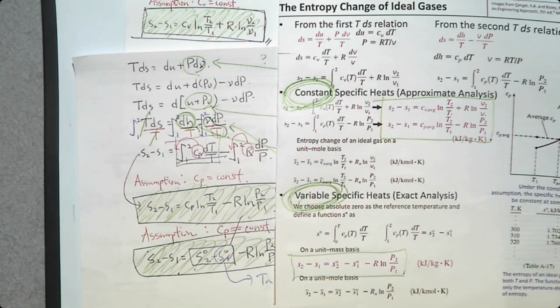On this slide, we studied how to determine the change in entropy because our assumption is that entropy should change. Is that assumption valid? Yes, whenever there is an irreversibility, whenever there is an energy waste, entropy should increase. Then what about if you have a reversible process? Then entropy remains constant. Then let's talk about an ideal case when entropy remains constant.